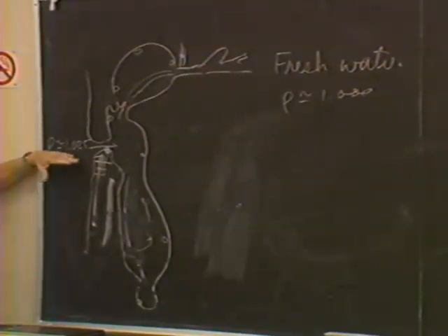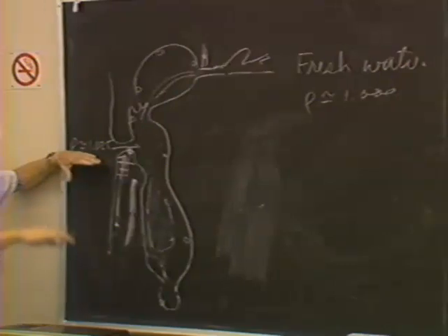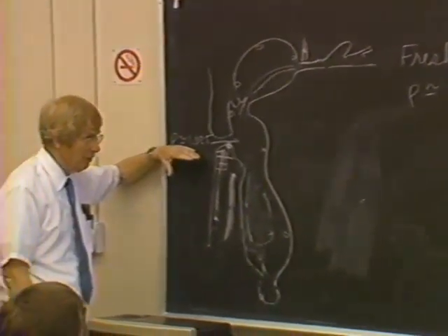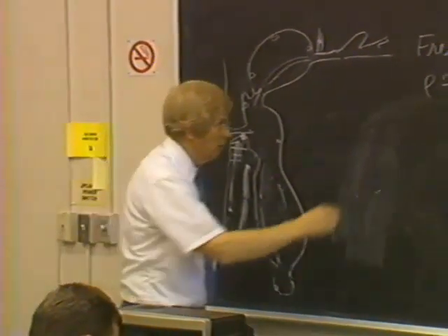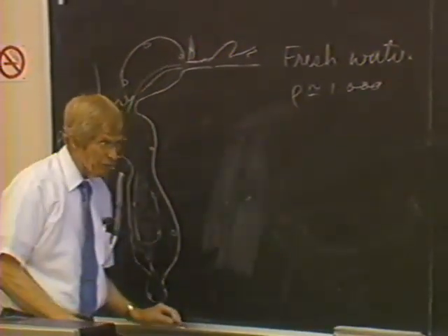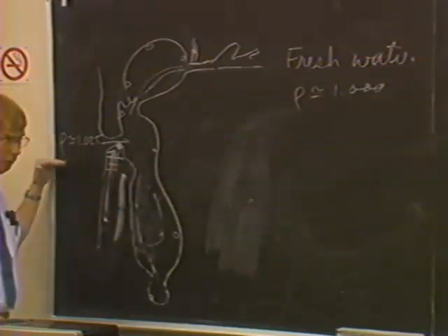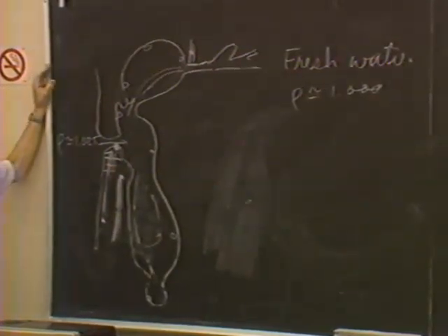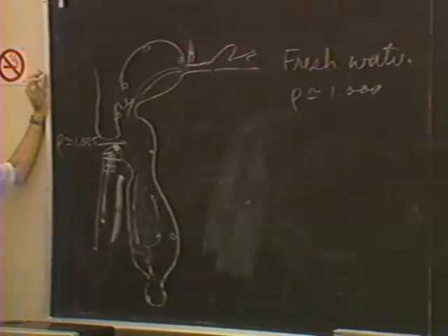It takes about 40 feet of seawater to make a 1 foot difference in pressure between freshwater and seawater. That is, 41 feet of freshwater will balance 40 feet of seawater. It doesn't sound like much difference, but it has a profound effect on the hydraulics of the system.